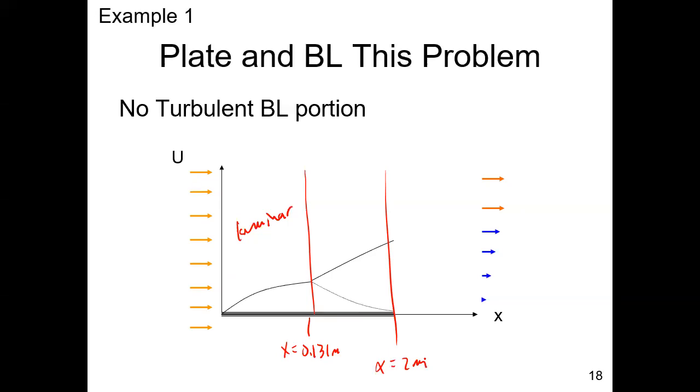And at the very end, we just have transitional boundary layer. So we have no turbulent boundary layer on this plate. It's too short or it's moving too slow. We did not get a boundary Reynolds number anywhere on this plate greater than 10 to the 7th. If we did, at that location, we would have a turbulent boundary layer. Okay. Is that the end of the world? Of course not. It's just the characteristics of the boundary layer on this flat plate.